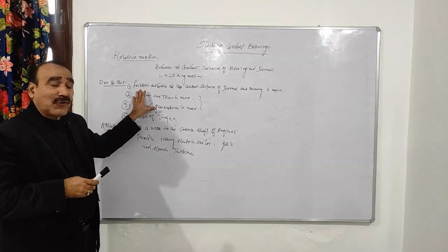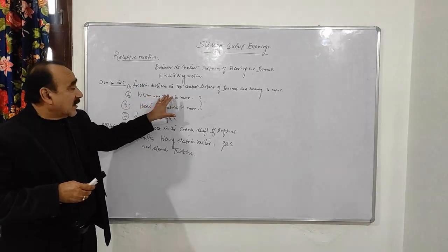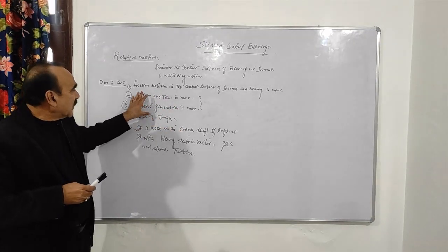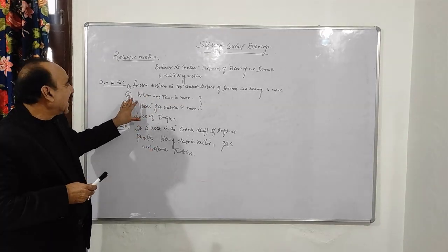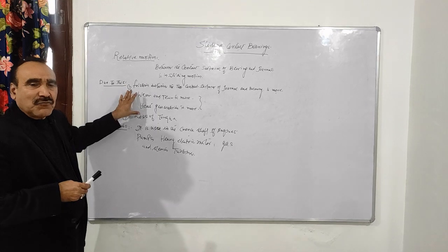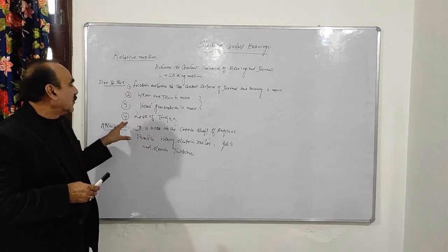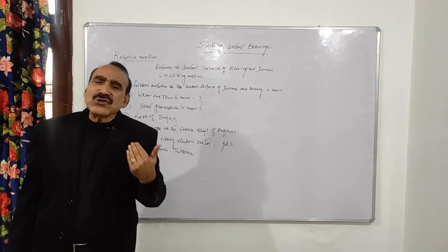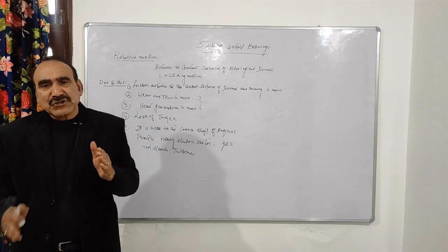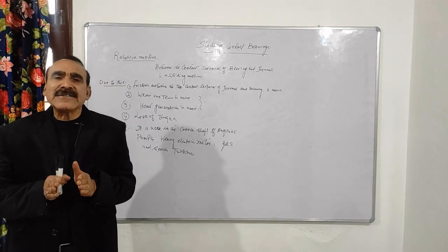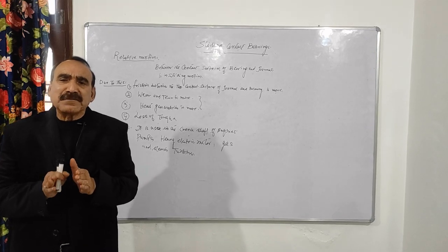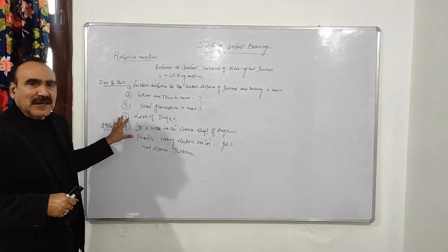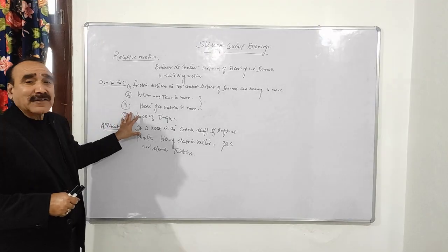So when the friction is more, wear and tear is more, heat generation is more, and loss of torque is there. So in order to reduce the effect of these things, we use the lubricating oil, or we say lubrication is required there, right? तो जहां पे जो lubrication part है, this is a very important part, or you can say lubrication plays a very important role here. So the design of your journal bearing depends upon the lubrication.